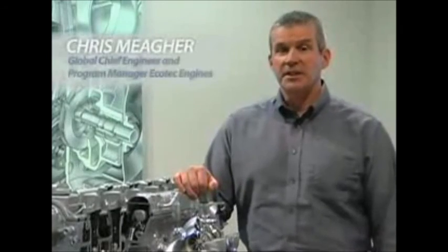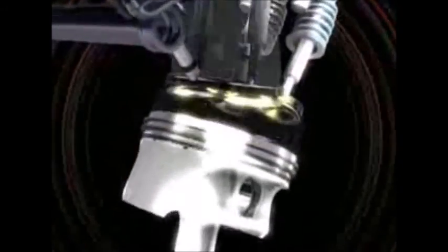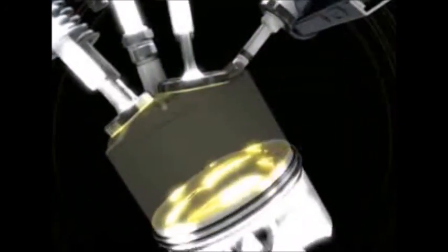Direct injection, or DI as we refer to it, is a really cool new technology that we're using to increase the fuel efficiency of our engines, but at the same time increase power and lower emissions. In the direct injection engine, we spray the fuel directly into the combustion chamber, which allows us to cool the intake charge. Therefore, we can increase the compression ratio in the design, and that's how we get the increased efficiency to run better fuel economy, more power, and cleaner emissions.